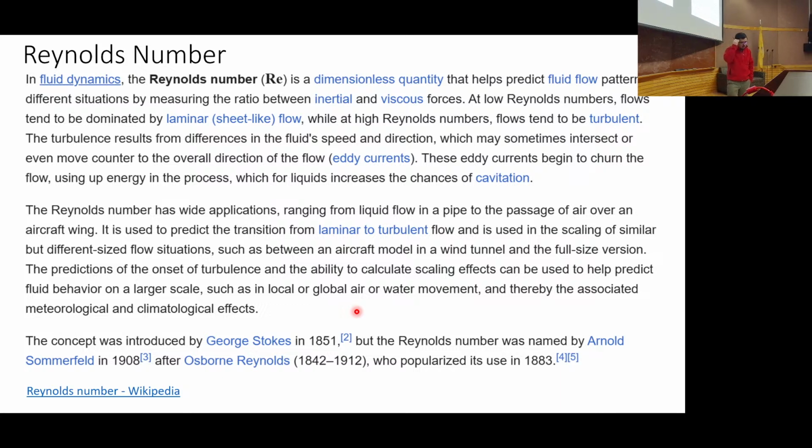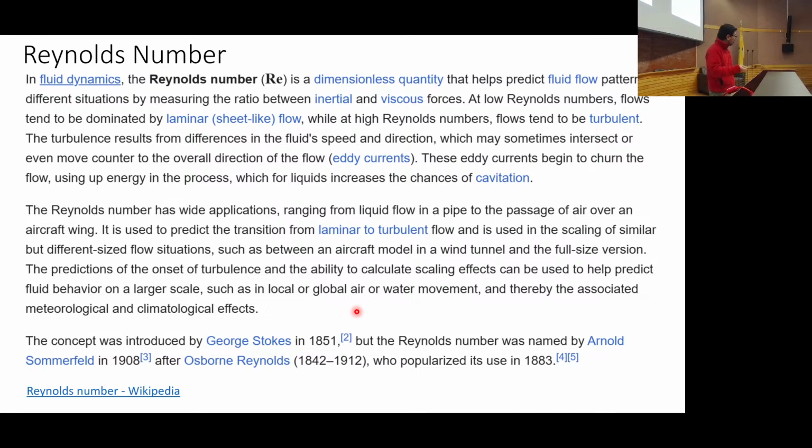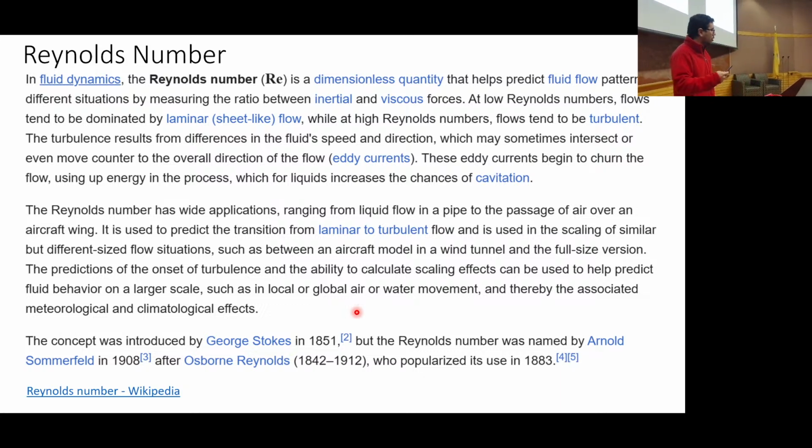You'll see really large Reynolds numbers when you have very low viscosity. So for a lot of the aerodynamic flows, when you have air, you're going to have a small mu, so that's going to jack up the Reynolds number pretty quickly. And then there are other situations where you're doing stuff in microfluidics or small chambers with water, which has a pretty small viscosity, and if you're in the hundreds or thousands, that's pretty turbulent, right? Like in pipes, 2400 was one of those numbers that you care about. So the Reynolds number gives us a clue of whether or not something's going to be turbulent or laminar in its flow.